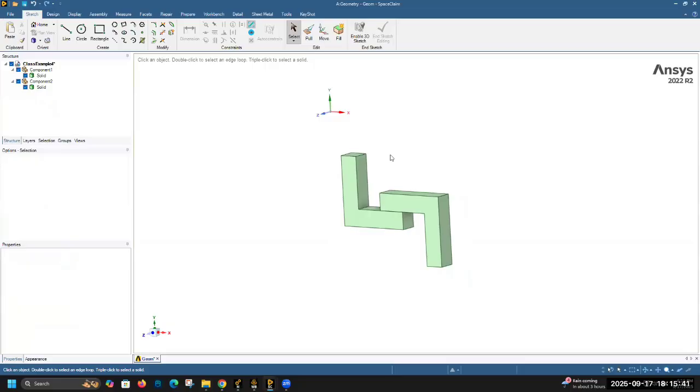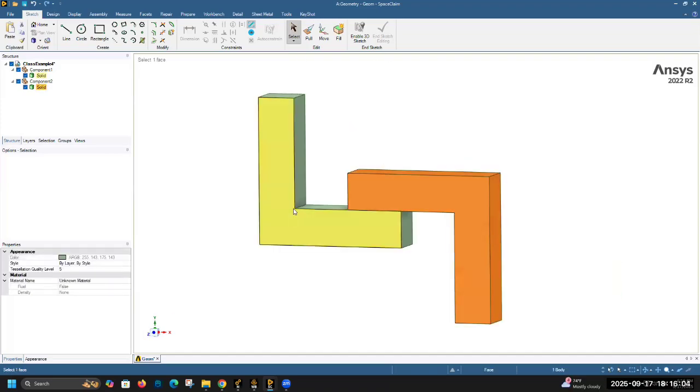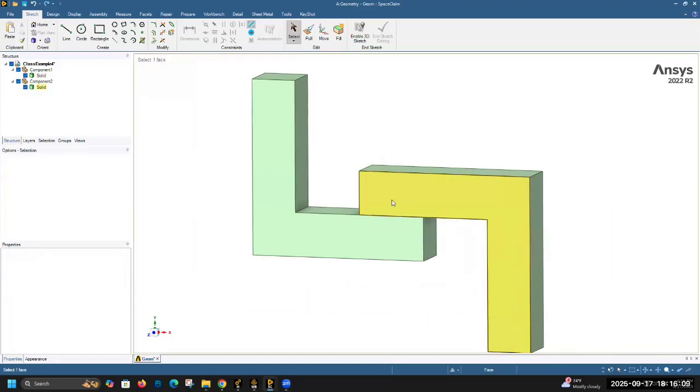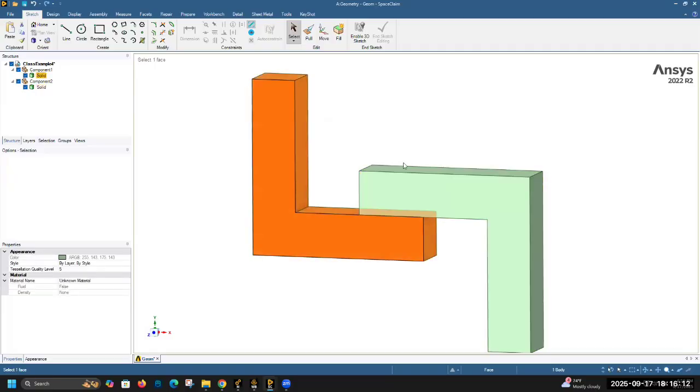Today we're gonna be looking at contacts in ANSYS, and generally contacts in FEA. Contacts are pretty hard. They always break. ANSYS Auto does the contacts usually whenever you open a file, but usually those contacts are wrong. ANSYS usually just bonds all your parts together. If you look at the CAD file here, this is two separate parts, right? And of course they're touching at this little interface. But if you don't tell ANSYS how these two parts need to interact, ANSYS will automatically assume it's bonded, which is not necessarily true. So that's generally what we're going to be going over: how contacts work and stuff like that.